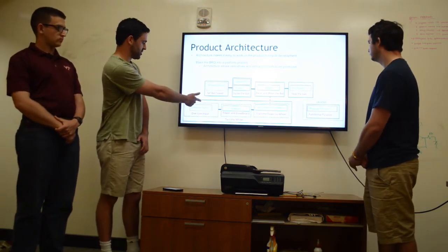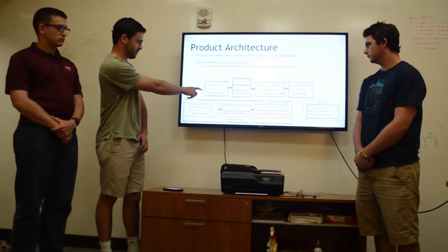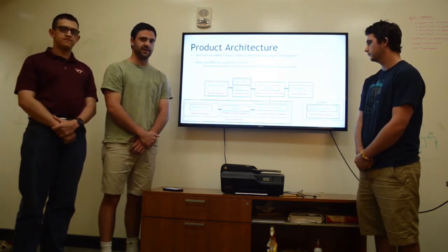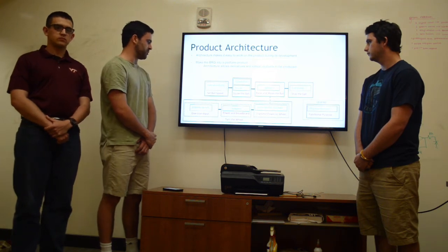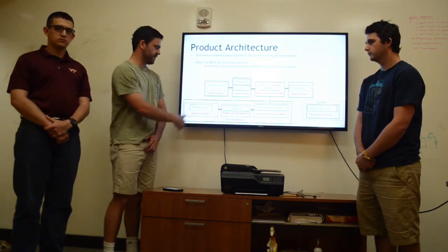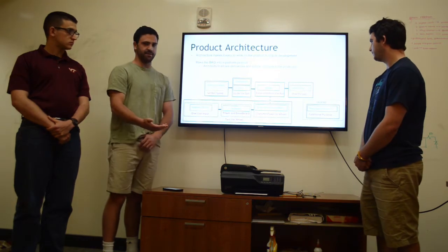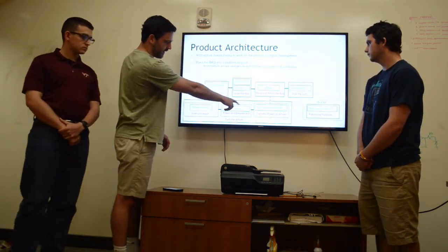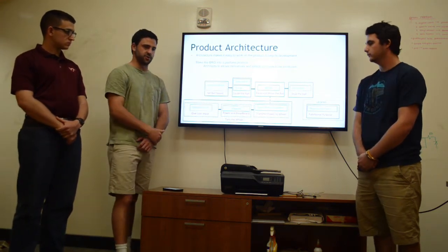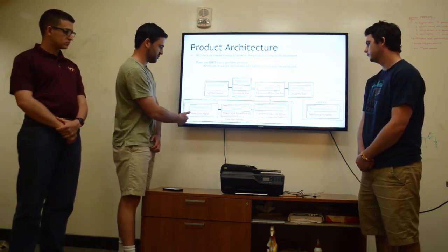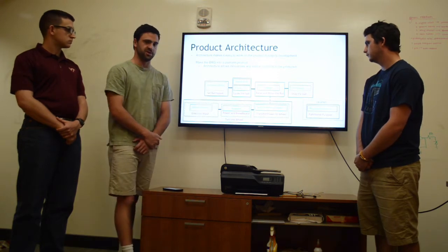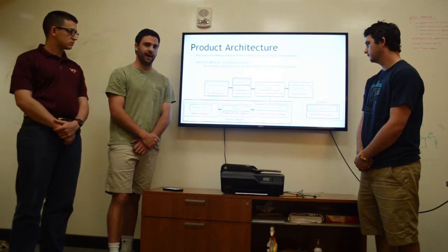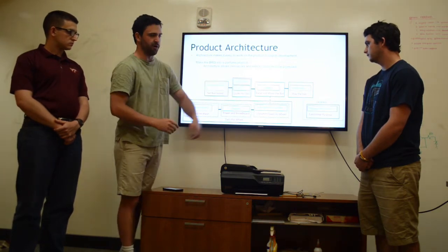So if you look at the sketch here, the blocks represent individual chunks, and red describes the function of the part, while blue describes the actual physical component. So for example, the entrance ramp sets the ball speed, and here to turn the wheel, which is over here, this entire chunk is made up of 3 individual chunks. The Arduino sketch, which gives user input, the Arduino itself, which is the power and breadboard, and the servo motor and axle, which transmits power to the wheel to raise and move the ball through the course.